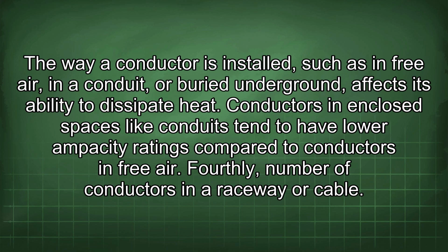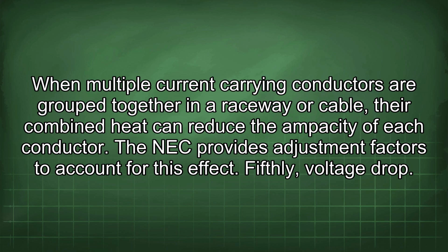Fourthly, number of conductors in a raceway or cable. When multiple current-carrying conductors are grouped together in a raceway or cable, their combined heat can reduce the ampacity of each conductor. The NEC provides adjustment factors to account for this effect.